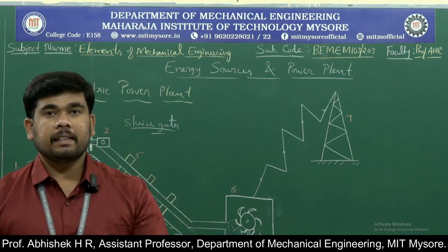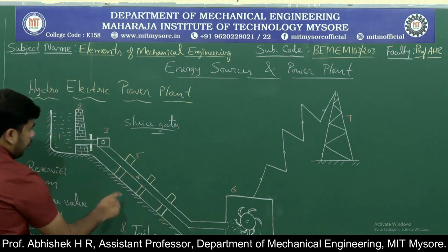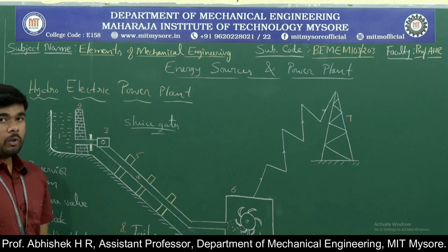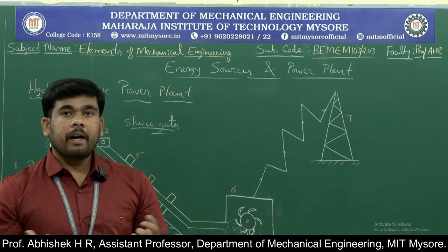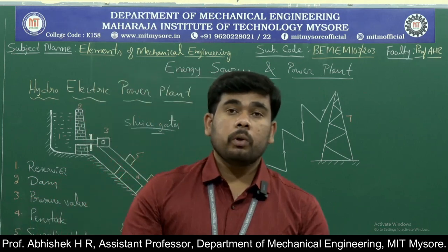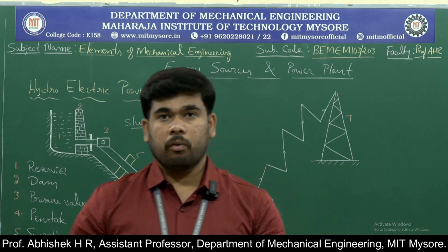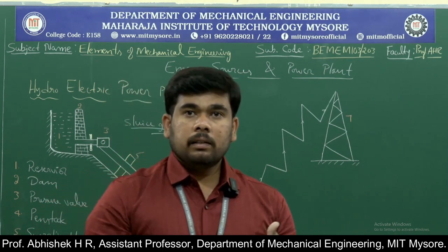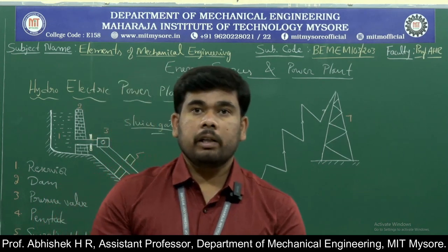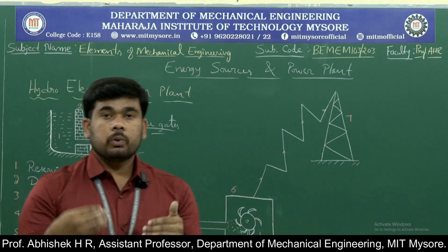Through this we release the water, and for this penstock we have number 5, the supporting blocks. Why do we need the supporting blocks? Since the pressure and the flow rate of the water are high when we release it from the reservoir, the channel of this cylindrical object needs to be compact within certain limits.